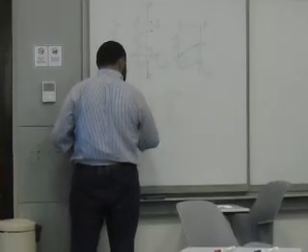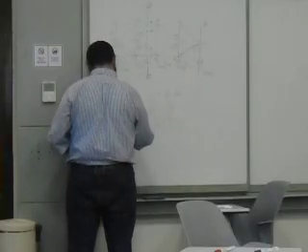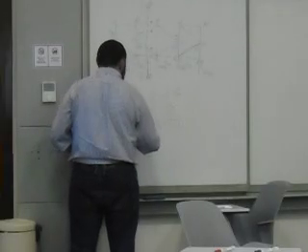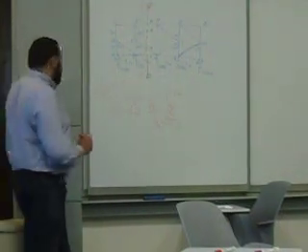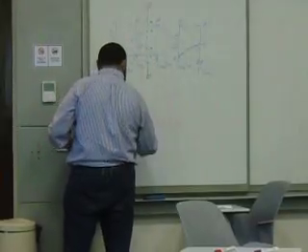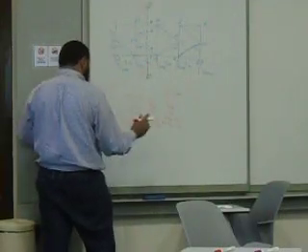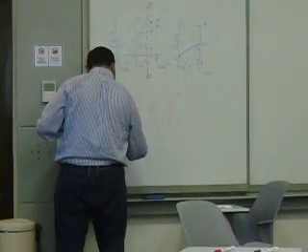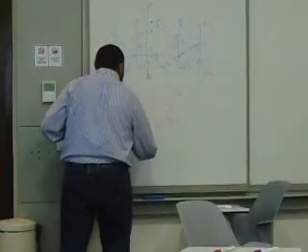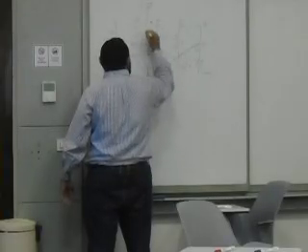So minus 6 FFG. So FFG is equal to 15 kilonewtons. Okay? Sigma Fx equals 0 equals FDH plus 15. That's it. There are no forces in the x, so therefore FDH equals negative 15. I'll go back to my original sheet and write it on them. But this is positive 15, and this is negative 15.